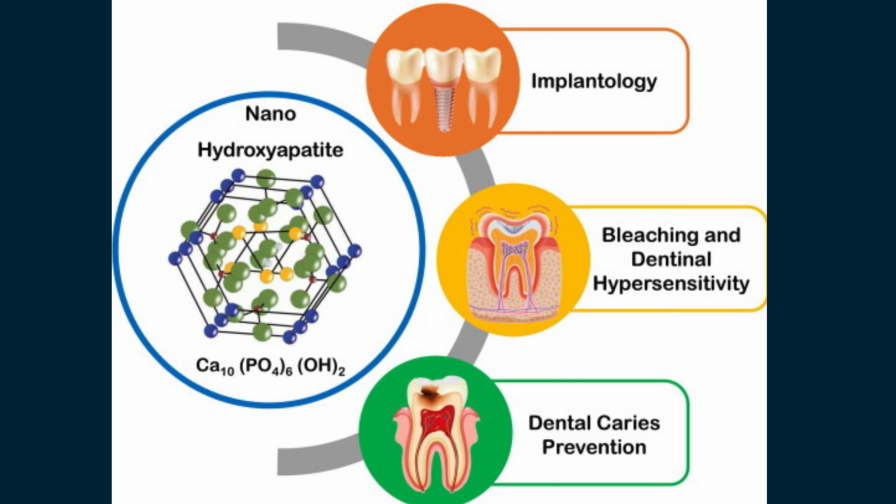At approximately 0.2 wt%, diametral tensile strength reaches a maximum, approximately 34 megapascals. Higher concentrations may lead to nanoparticle agglomeration and reduced curing efficiency due to increased opacity. Hydroxyapatite nanoparticles also demonstrate bioactivity, promoting remineralization of demineralized dentin and interacting with collagen fibrils at the adhesive interface. Surface silanization further improves adhesion to the resin matrix.